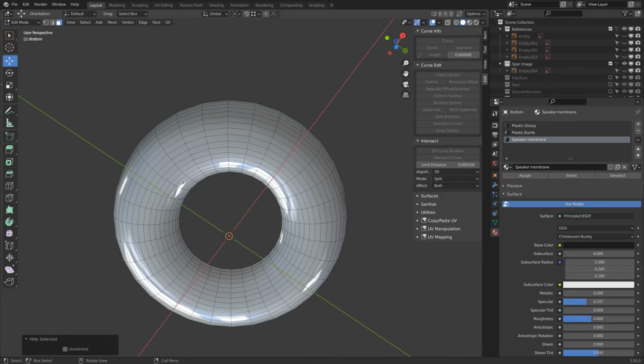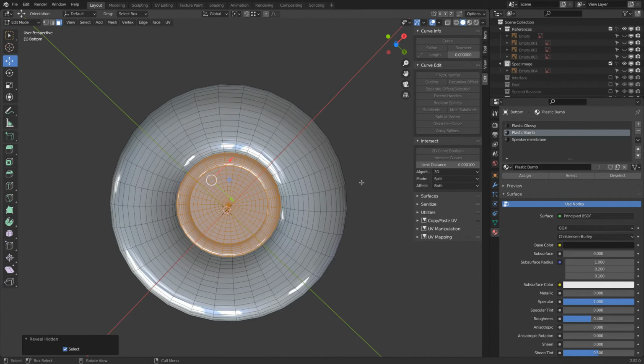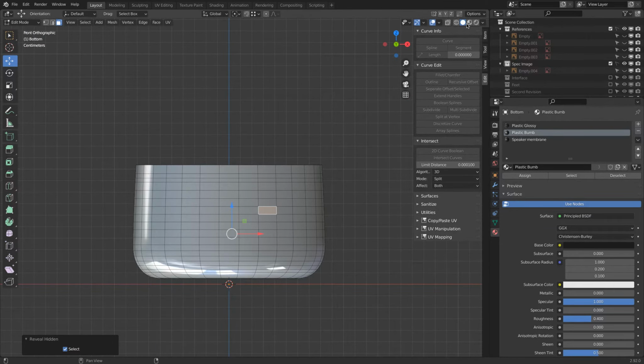The only thing is, when you in general press Alt H, let's say even here I selected something, H, and Alt H, it shows it all. So this is the downside of this approach when we hide the mesh inside the body, which is why I, for example, prefer separating the meshes, and it's easier to texture because, as I showed you, I can glue them back together very easily. Very good.